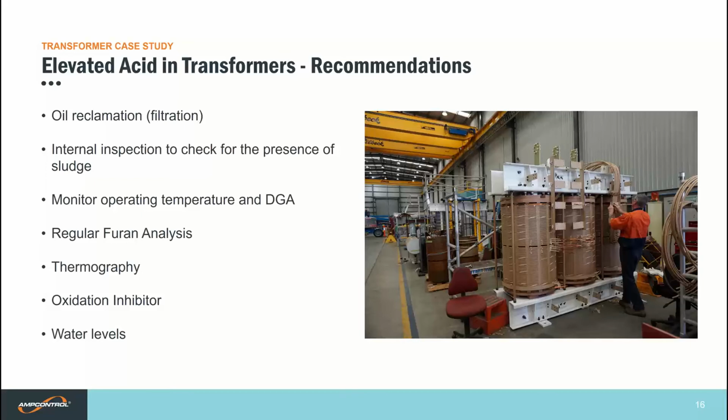Remember, under most conditions, transformer oil will not undergo oxidation if sufficient inhibitor is present. Maintain low water levels in the paper and oil, as elevated levels can increase the breakdown of the paper by acid.